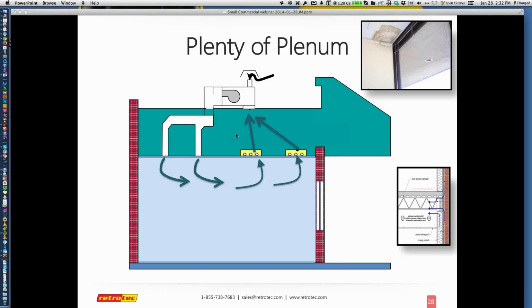The illustration I have now refers to drop ceilings that are used as a plenum, where all the return air is brought back. You can think of this whole drop ceiling, up in green, as an area where all of the return air gets brought up on the other side of the drop ceiling, moves around anywhere, and finds its way back to the return path. It's conditioned and brought back into the structure with the white ducts here.